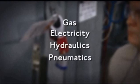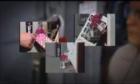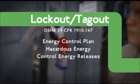They may have to be disconnected and locked out according to OSHA's lockout-tagout standard, which deals with the control of hazardous energy sources. The lockout-tagout standard requires companies to develop an energy control plan, which identifies workplace hazardous energy sources, including high-pressure gases. The energy control plan also includes procedures for controlling potential energy releases.